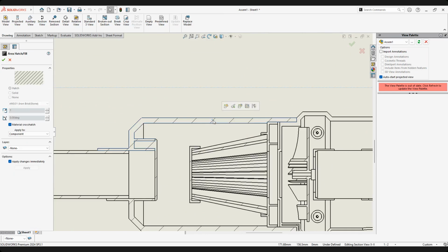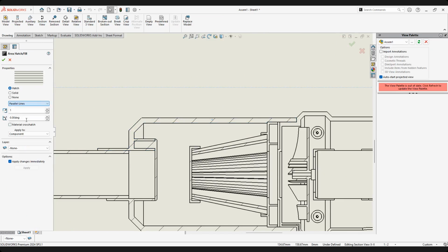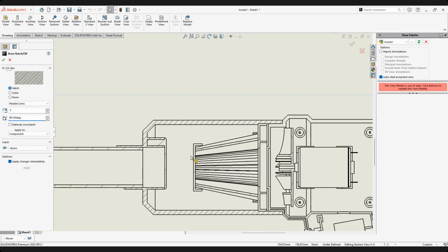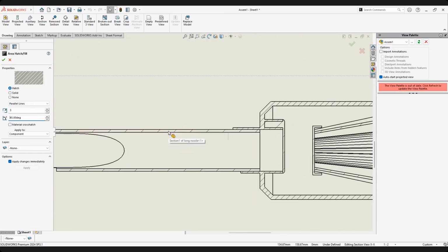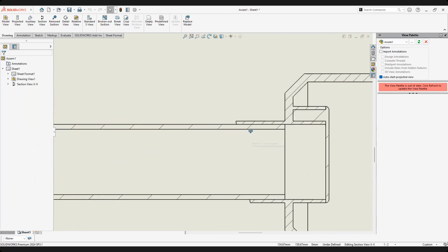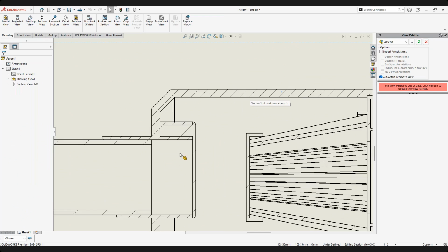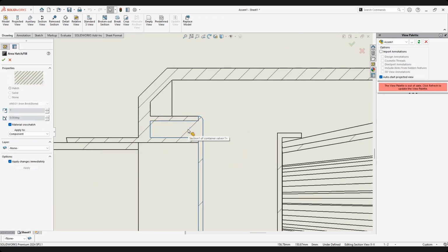I select there, select this one, but this one I don't want to use the material cross hatch. I will use the most standard parallel lines, and I go for density of 3. Increase the density to 3. I go for 45. Go for 45. So that one. Okay, about the other one here, I click OK first. Okay, this is the container. Can you see the valve? The valve cannot share the same section line.